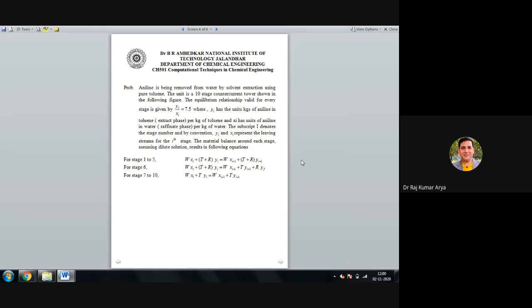So at this plate, you have also inserted something coming in here, that R plus F, which was the new material which you have added. Something was already coming in, so you have added one more component from outside. This is the condition from where you are feeding the material in. Now that would have a separate equation. Once you have fed it in, your extra would be added somewhere in the yi from that plate onwards.